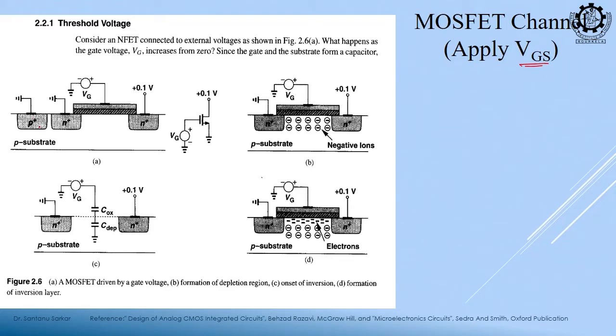See, between this substrate and this source, or substrate and this drain, we do not want any current. We want our current to flow through the channel, right. In BJT if you recall, collector and emitter current were flowing, right. So, similarly we want drain current and source current. Okay. And in this MOSFET, as there is an oxide region, so gate current is 0, right.